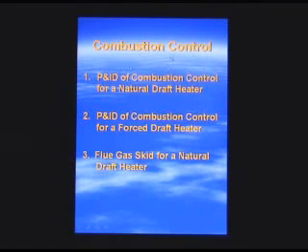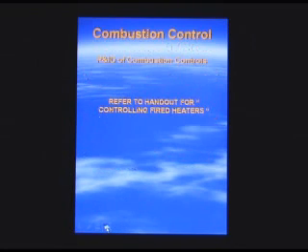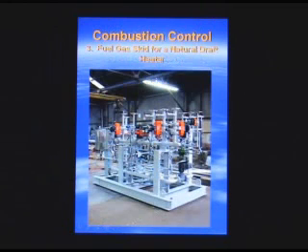So basically, again, the P&IDs are shown on this handout, which I note here. That covers both the forced draft and induced draft P&ID controls. Again, this is a typical fuel gas skid that's used on a fired heater. This in turn is controlled by a burner management system device. Usually it's a PLC or a more sophisticated one that has a DCS interface.